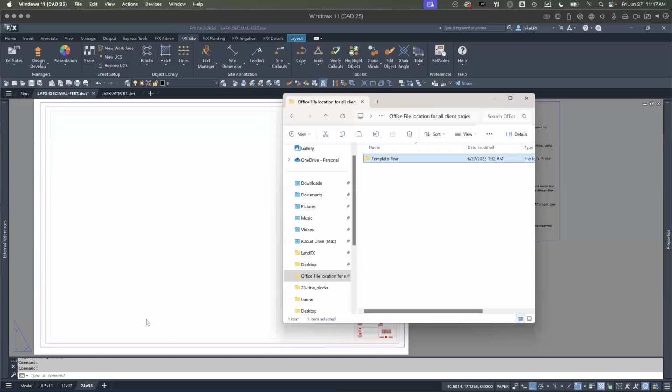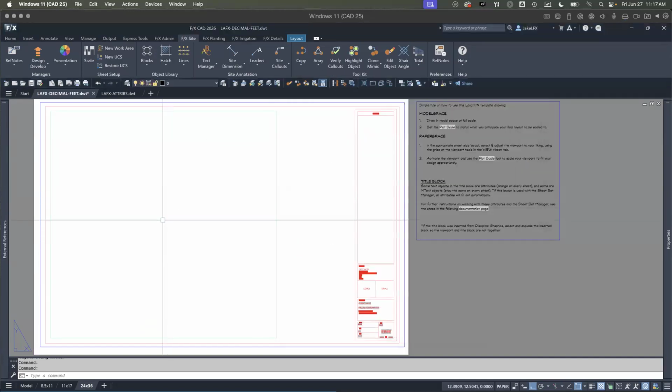And that on-off AutoCAD command is a field display system variable. So when set to 0, the field gray background color will not show. When set to 1, it will show. And that is awesome.